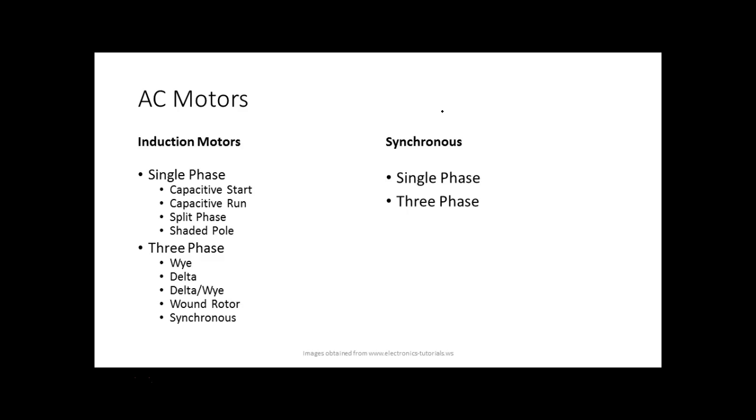So single phase motors, we have what we call a capacitive start, we have what we call a capacitive run, and we have a split phase motor and a shaded pole motor. We probably won't look at a shaded pole motor. I'll show you it, but we can't reverse those electrically. A shaded pole motor, the only way you can reverse it is mechanically. So we're looking for the motors that we can reverse electrically, right? Understand?